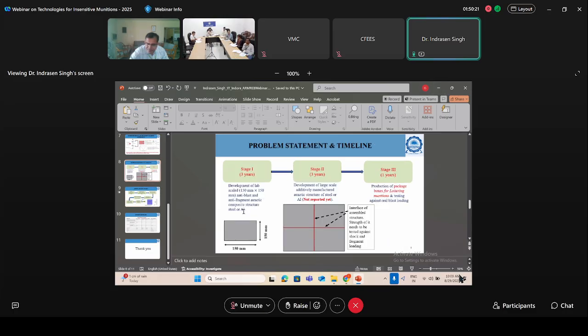Aluminum setup is very expensive because reflectivity of aluminum is very high. So printing aluminum structure with thin cell wall is quite challenging. We had to do some pre-processing, and that increases the cost of machine setup. That's why we're keeping steel also.